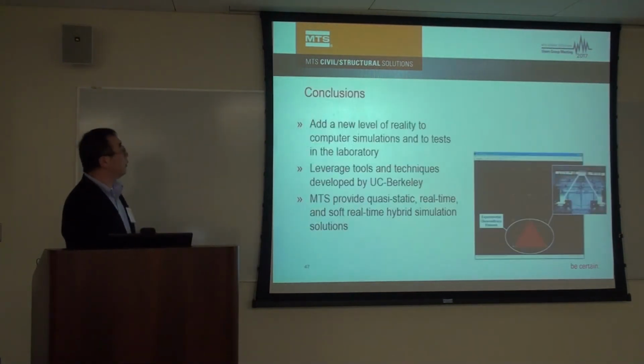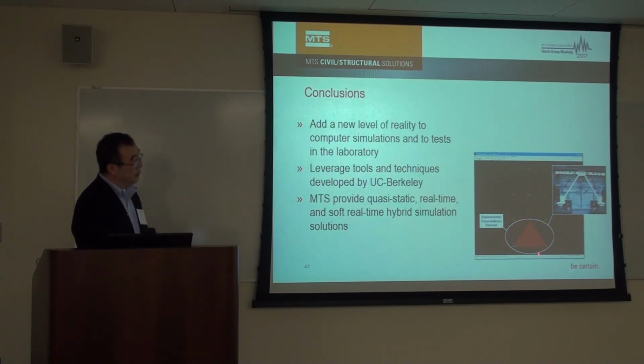So, in conclusion, hybrid simulation makes the computer simulation more accurate because the really nonlinear component is tested in the lab, and it makes the lab testing more accurate because the loading is calculated by the FEA model, so it's a realistic loading.